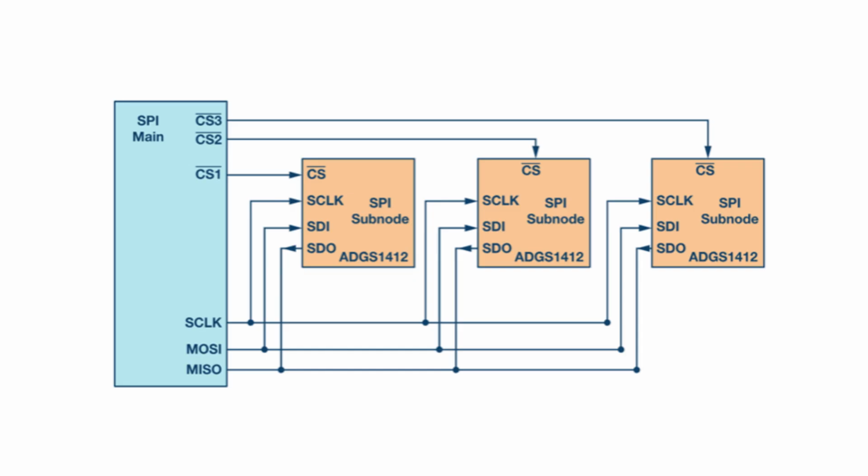Precisely. So, if your microcontroller needs to talk to a flash chip, a display, and an ADC sensor using SPI, they'd all share the SCK, MOSI, and MISO pins. But you'd need 3 separate GPIO pins on your microcontroller dedicated to the CS lines for each of those 3 devices. A couple of tips for reliable multi-slave.